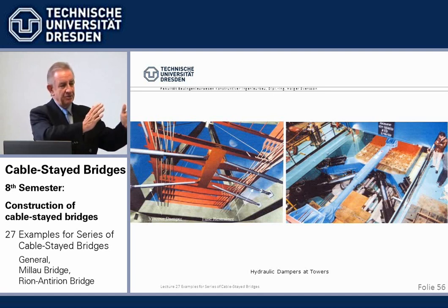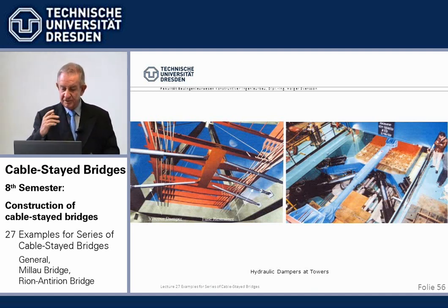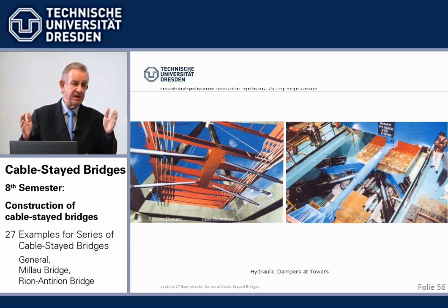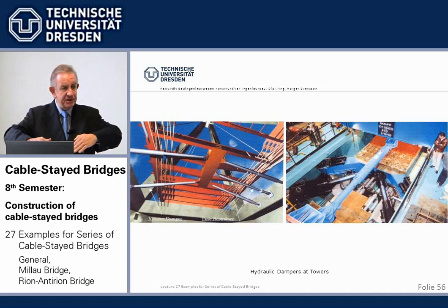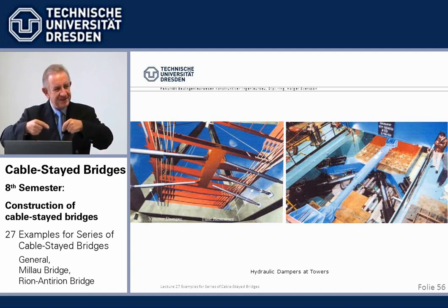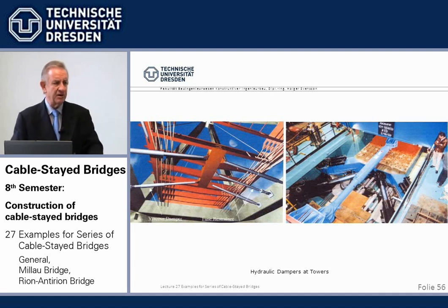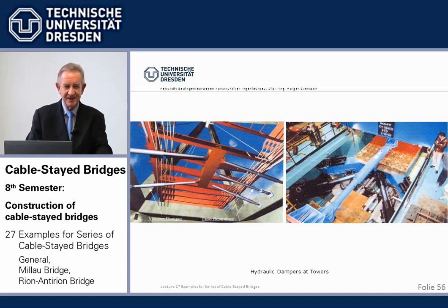Of course, we have 2-meter movement possibilities, movement joints at the end with bumpers. So in longitudinal direction, the beam is free, which gives it a low eigenfrequency, so that it doesn't respond to fast movements of the earthquake when it has this long period. We did this with a desired failure joint for the Pasco-Kennewick Bridge.